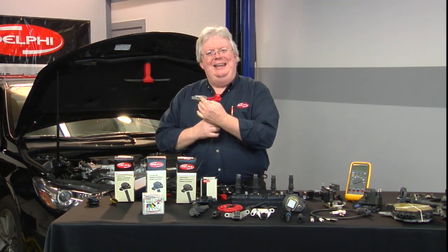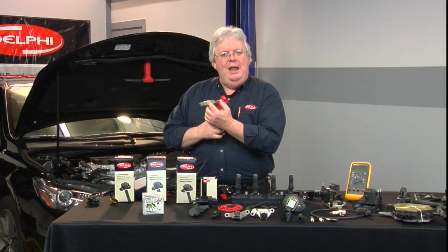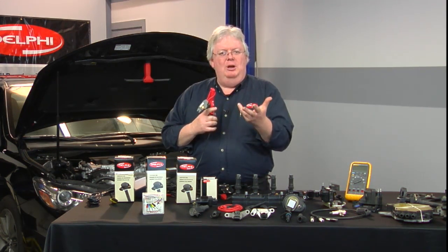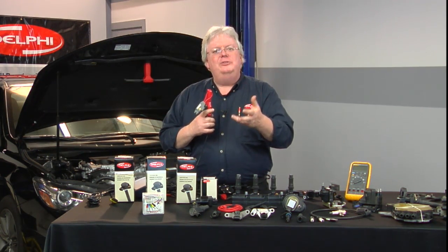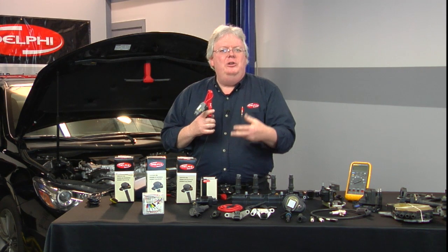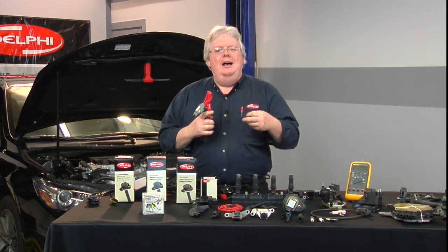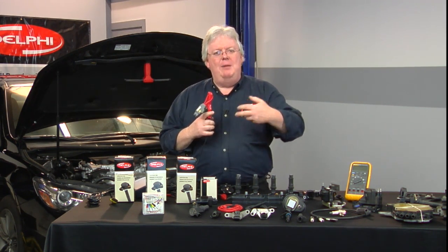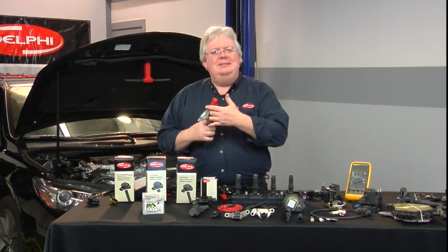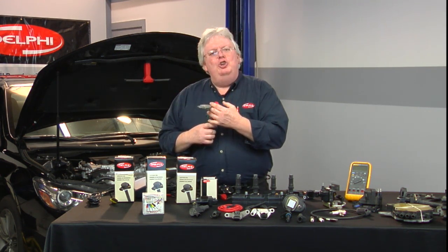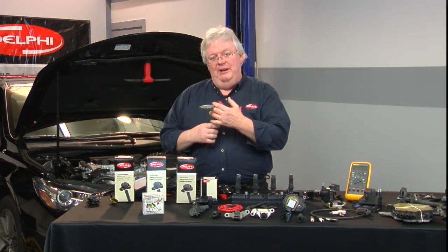So now all the current goes through this loop, and then with your scope and your inductive amp clamp, go around there like that. Take a second channel of your scope and go to number 1, either the trigger wire if it's a smart coil, that's 3 or 4 wires, or if it's like the Ford 2-wire, go to the primary ground pulsed signal from the primary driver inside the PCM, and that will be a sync pattern. You know which one number 1 is, so with a firing order, you can